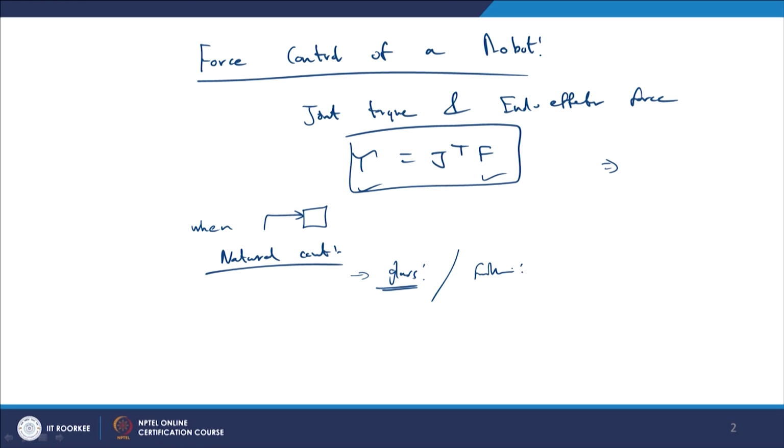So, the contact force must be applied in such a way that depends on the stiffness of the environment. So, the stiffness of the environment gives you the natural constraint, but at the same time, in order to have the glass to be cleaned, the direction towards the glass should be controlled.